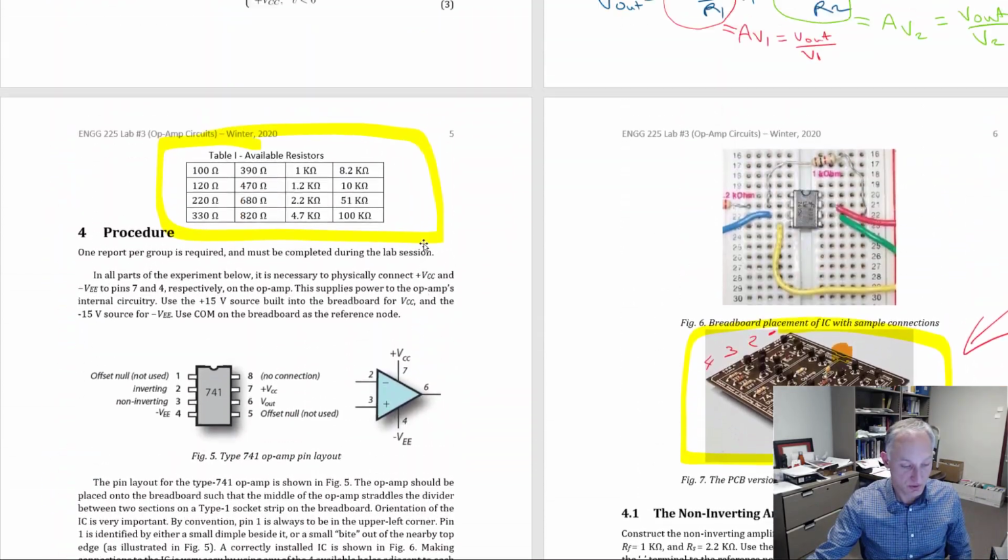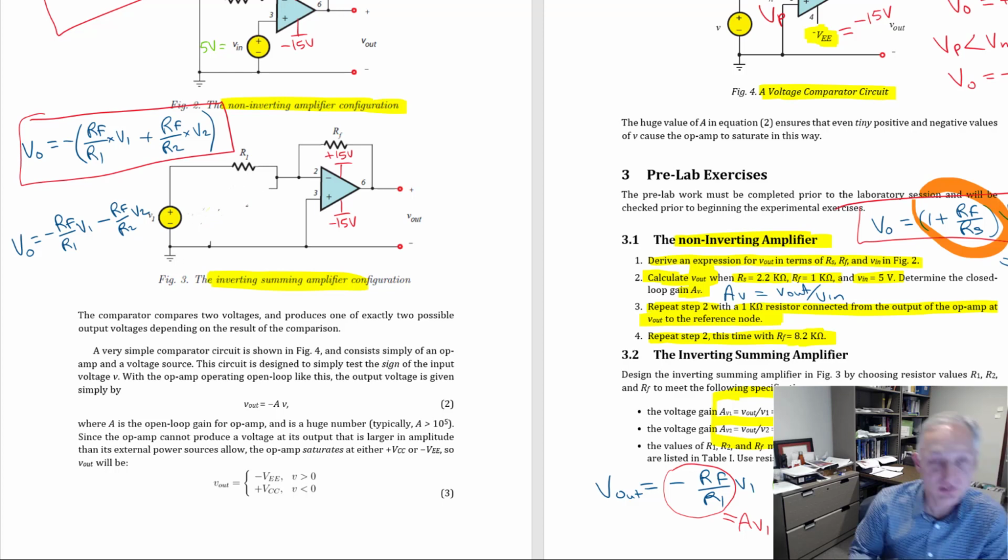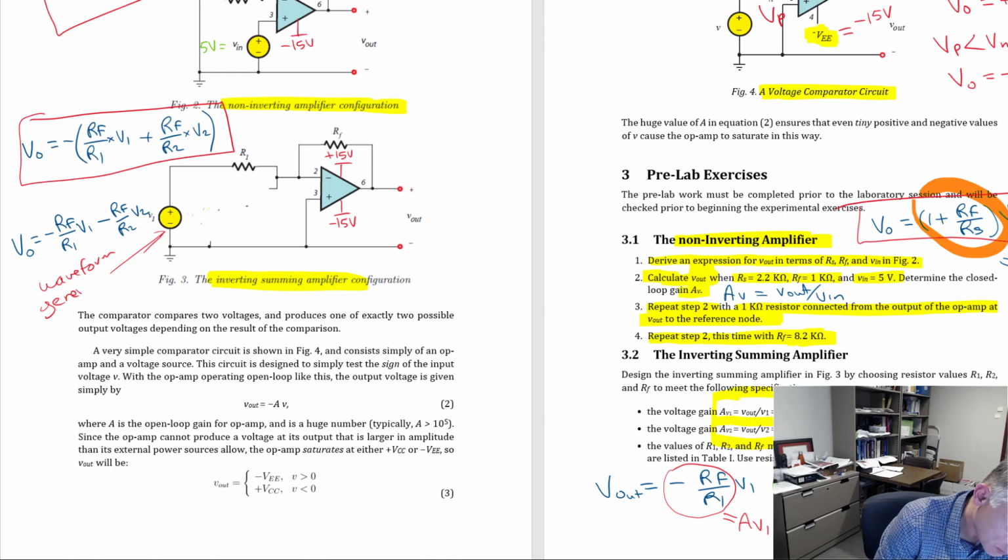So you're going to be building this part of the circuit. You're only going to draw the part of the circuit that's visible here. You're not going to build this second part of the circuit yet. So that's going to be the minus 11 times amplification. This input here is going to be the waveform generator, and that's going to be the cardiac signal.